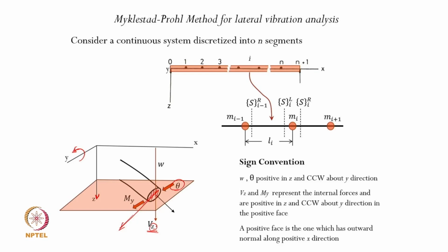But we are not going to look into that part as yet, but still, as a general convention, we put these subscripts z and y for the shear force and bending moment to appropriately and precisely label them. So My being the bending moment about this y axis, it is considered counterclockwise on the positive face as the positive values.